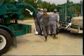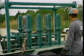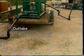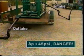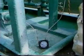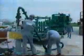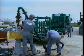The filter system is extremely important, especially in sandstone matrix acid treatments. Here, several 2-micron filters remove solids from the treating fluid. These solids could severely damage the formation. Further, if the unit's intake and outtake pressure differential were to exceed 45 psi, there would be a danger of collapsing the cartridge filters and contaminating the reservoir. Therefore, pressure differential is displayed on a gauge and monitored throughout the job. Finally, acid exits the filter system through high-pressure lines connected to the wellhead.